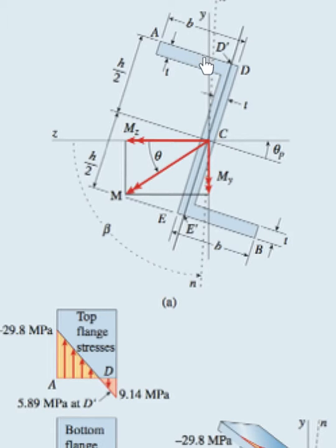And therefore every surface that is on this side will be seeing compressive stress because the four fingers are going into the page on this side of the y-axis. Therefore, this component will also contribute to the compressive stress at point A. Therefore, both of them are negative, and they will result in a larger compressive stress.